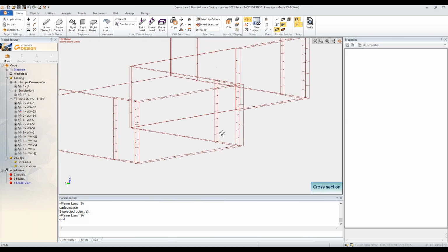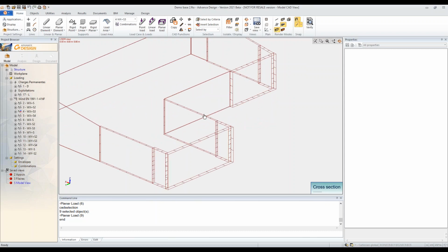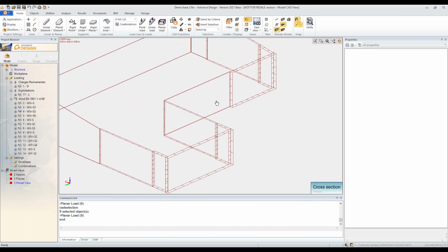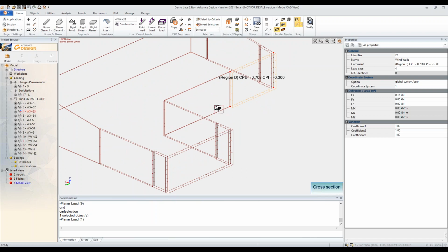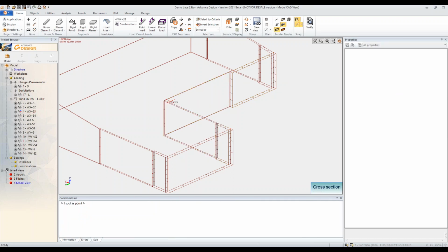Remember that the wind is blowing and we have a small deviation like this. So this whole part of the building is actually protected because of the setback. And because of this protection, it cannot be zone D. It's actually zone C, because it's zones A, B, and C that are going on. And the length of the protection, like the 12 meters we have here, is not random. It's actually the 12 meters from there that we bring back all the way to make it zone C.